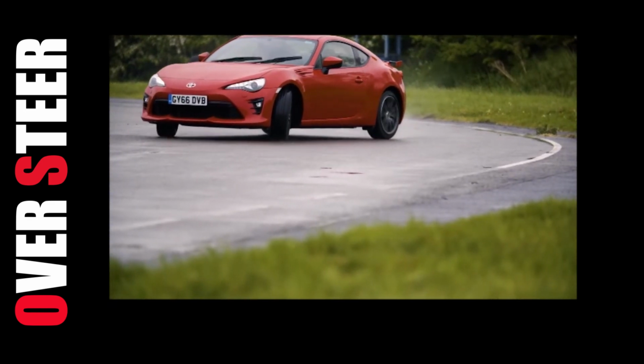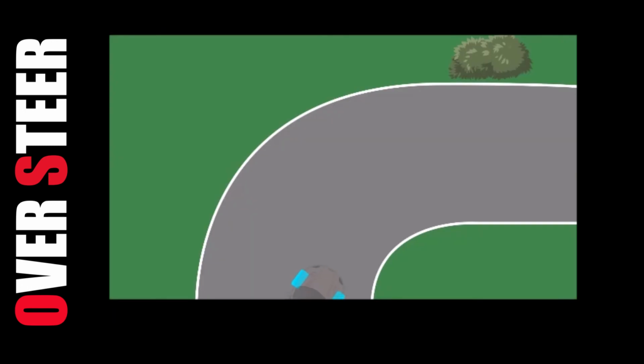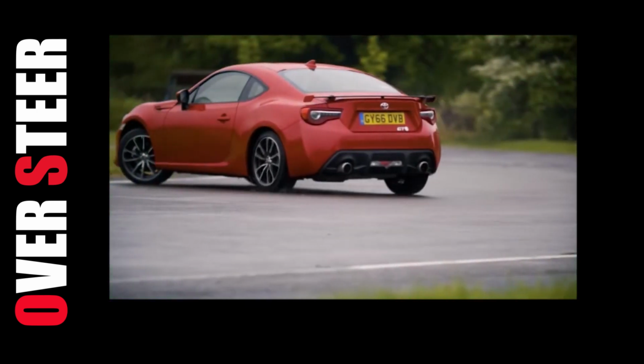So what is counter steering? As you can see, we're going into the corner, and you'll see we now need to turn our wheels in the opposite direction that we were actually traveling in. So you can see we were going around a right hand side corner, but the wheels are now actually pointing left. If you don't do that, your vehicle will spin out.